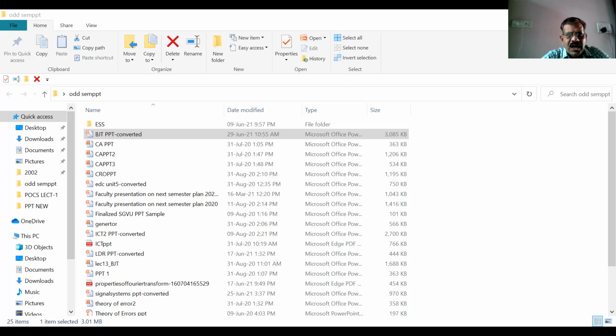In this graph, VBE versus IE characteristics is called input characteristics. IE increases rapidly with base to emitter voltage VBE. It means input resistance is very small. So emitter current is almost independent of the collector to base voltage.